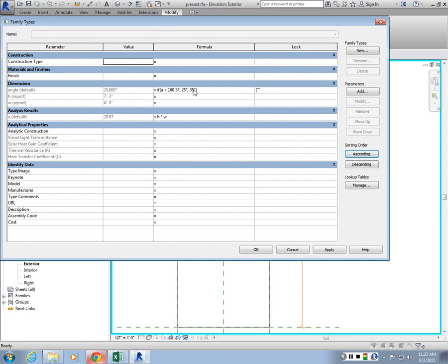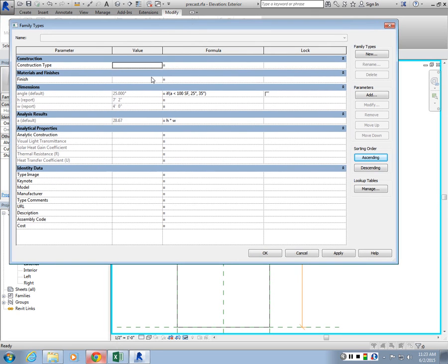Just set this as fixed angle values, and my advice would be to go back to the facade you want to create, look at the average panel values, and think about what angle you want to set for those. For the small area values, like the stuff that I had less than 20 square feet, they could extrude even more. But the large panels you don't want to be gigantic, so you want the angles for them to be smaller.